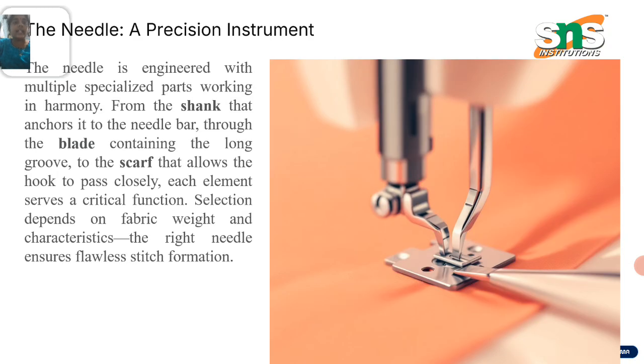So the first is the needle. The needle is engineered with multiple specialized parts working in harmony. The shank is the topmost part of the needle that anchors it to the needle bar. The blade contains the long groove of a scarf that allows the hook to pass closely. Each element serves a critical function. Selection depends on the fabric weight and characteristics, and the right needle ensures flawless stitch formation.